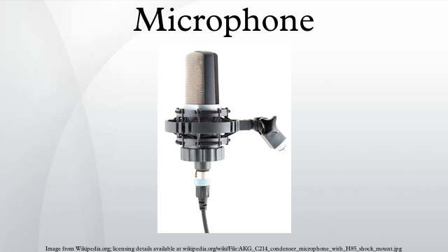The clipping level is an important indicator of maximum usable level, as the 1% THD figure usually quoted under max SPL is really a very mild level of distortion, quite inaudible especially on brief high peaks. Clipping is much more audible. For some microphones the clipping level may be much higher than the max SPL. The dynamic range of a microphone is the difference in SPL between the noise floor and the maximum SPL.